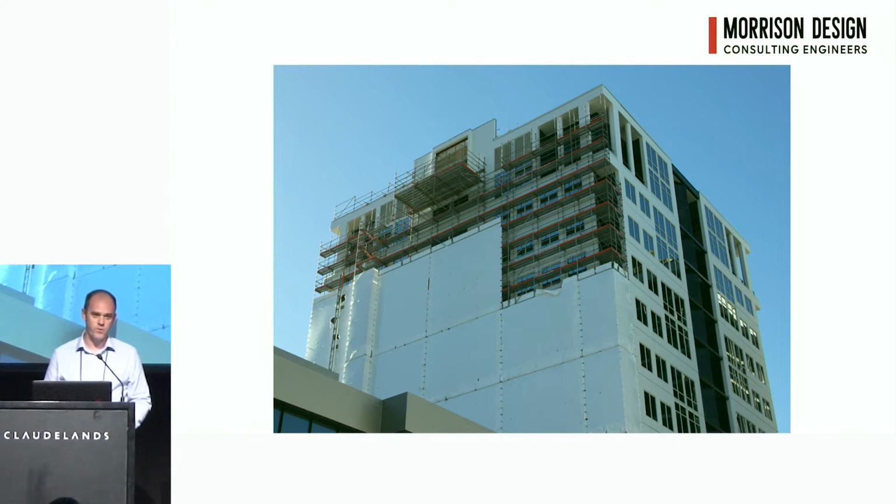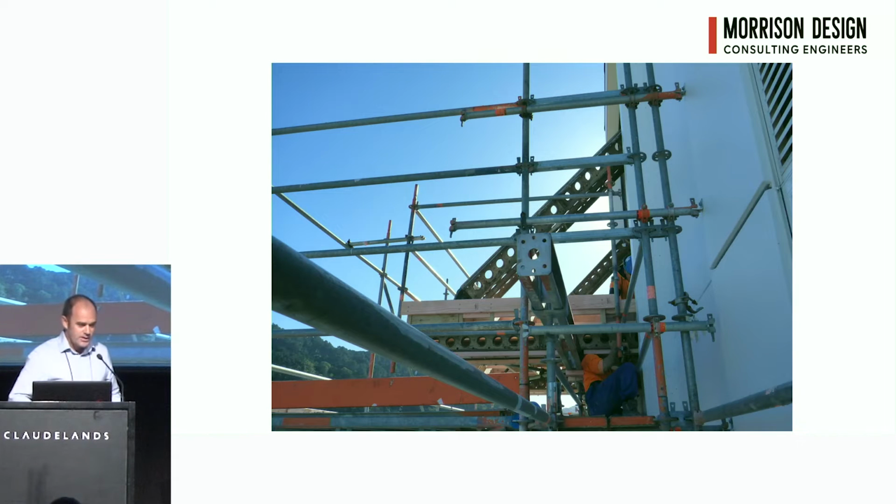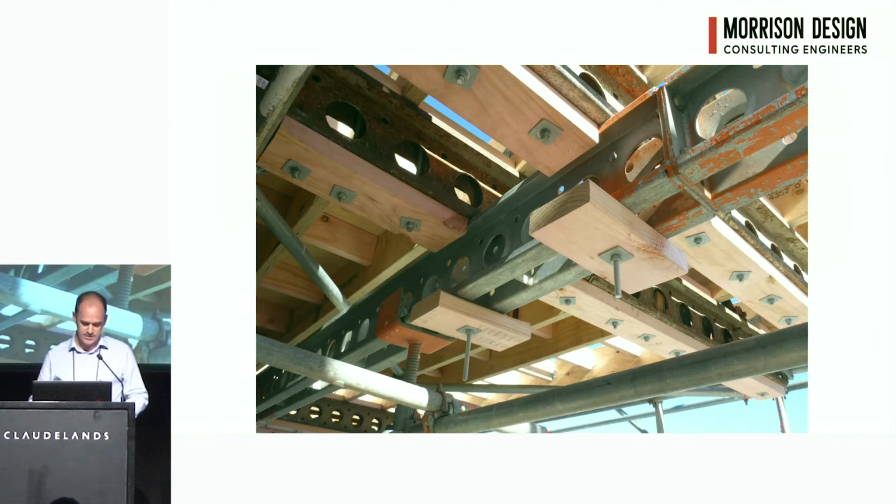We've got guys with fall arrest systems. There's big safety from falling from height risks. And as building designers, we really need to be thinking about how we can mitigate this risk of having people carrying out this sort of high-risk construction work. You can see we've had to install some soldier beams up. This is the same platform. We've had to put chemical anchors into the building, so we've had guys on harnesses installing those chemical anchors. Big beams spanning between these trusses we've got coming off the building. It was quite an undertaking.